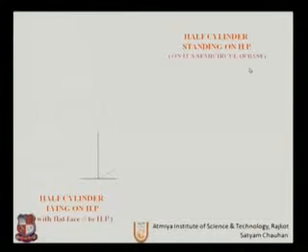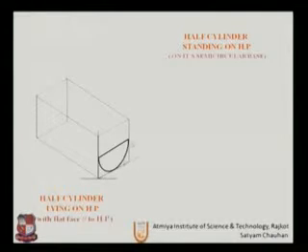Let us draw first a baseline, H and L isometric axis, and a rhombus. To produce the top and the base, let us draw boxes, and now produce the semicircle with the rhombus method we learned before, to join and copy the same view on the other side. So this will be the half cylinder to show, and join the outermost line.